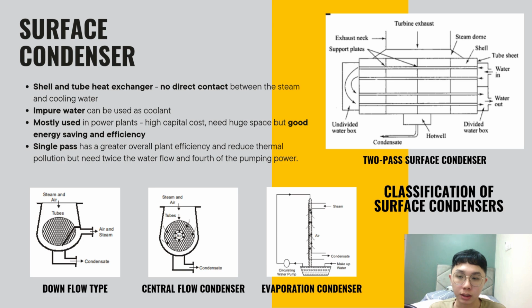In this condenser, the steam passages are all around the periphery of the shell, and the air is drawn away from the center of the condenser. The condensate moves radially towards the center of the tube nest. Some of the exhaust steam moves towards the center and meets the undercooled condensate and preheats it. Thus, it reduces the undercooling.